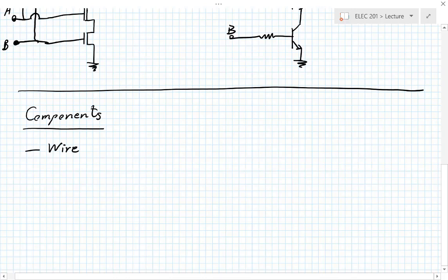Now, it's surprising how much misunderstanding happens when we deal with wires in circuits. So it's something that requires really special attention. I think, in fact, it's the most poorly understood element. Now, what is a wire? An ideal wire is something that we use as a simplification to represent pieces of conductors with almost no resistance to the flow of electric charge.